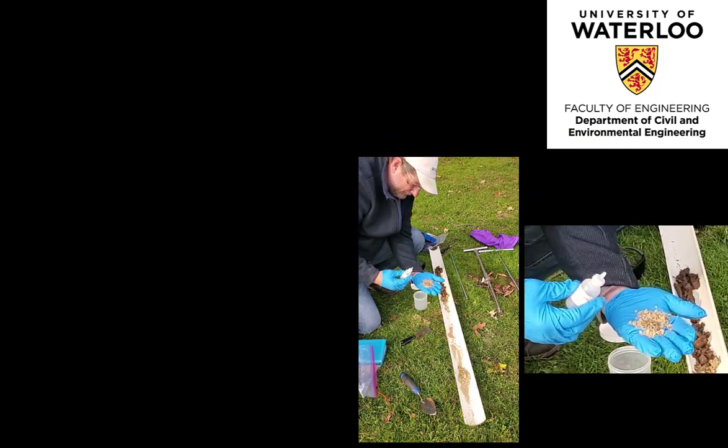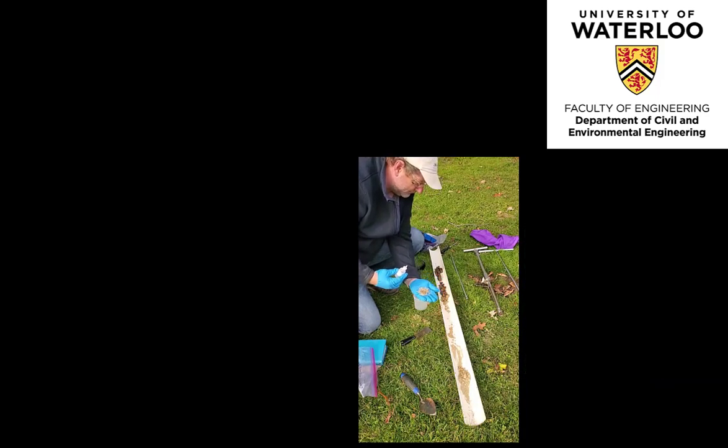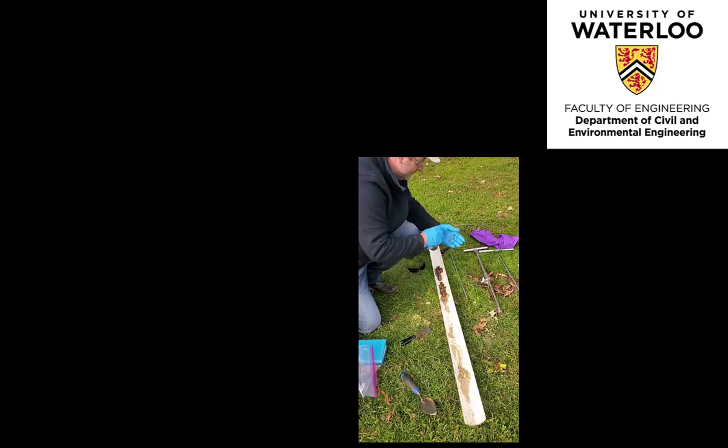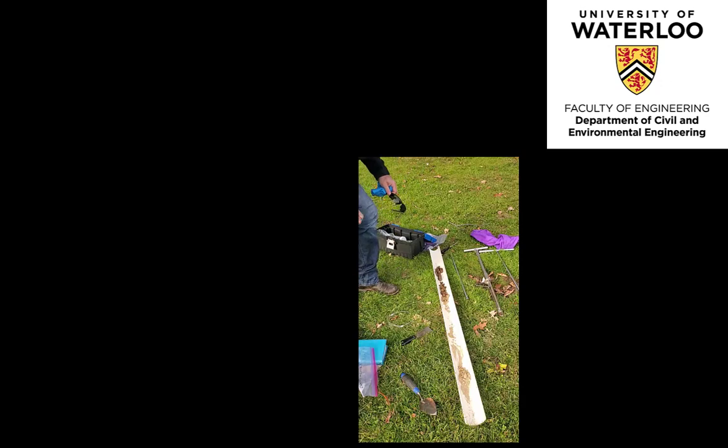It is noted here that all of the field tests demonstrated could have been undertaken on each of the soil horizons identified in the core log, hence the A, E, and B horizons, albeit the B horizon would need to have been advanced further. However, this instructional video was focusing in on the infiltration characteristics of the soil, which were considered to be dictated for this particular coring example by the E horizon.